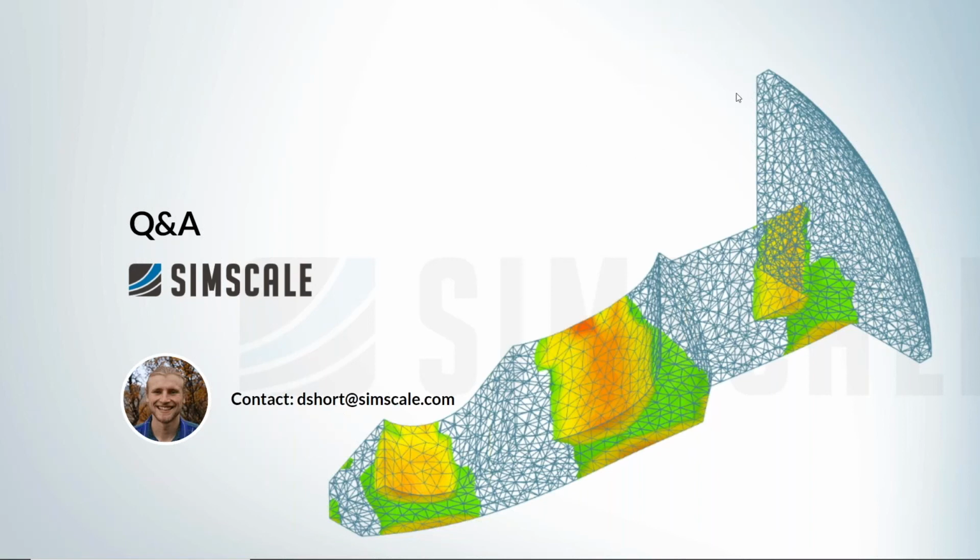When we saw it, about a quarter of the way through the simulation, we're seeing that peak stress where it's at its full deformation. It would actually be more accurate to add smaller time increments around there, so we actually resolve the physics with a little bit more resolution. But this is an arbitrary choice. For those initial design iterations, I'm just going to use a fairly standard approach with constant load increments. But as we move further into validation and quality assurance type exercises, then we would start looking at that kind of physics resolution.